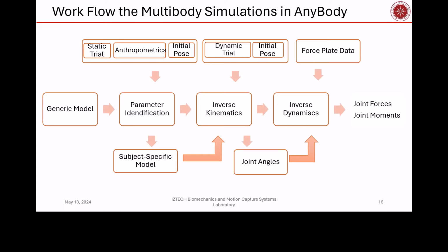Alican, thank you. The multibody simulations are performed in the AnyBody modeling system. The workflow of the process is as seen. We can divide this process into 3 main steps: parameter identification, inverse kinematics, and inverse dynamics. Each step builds upon the previous one.